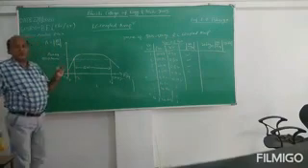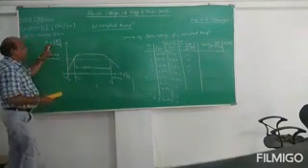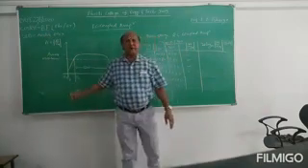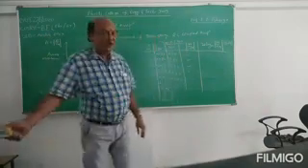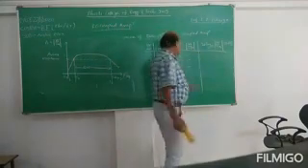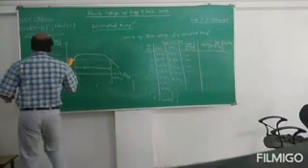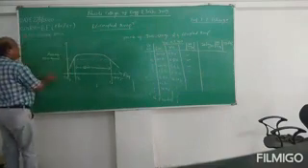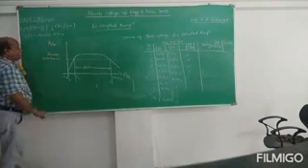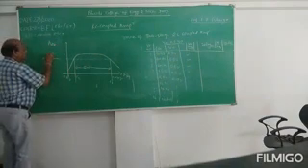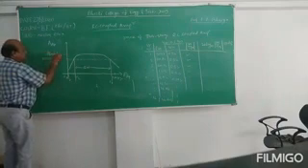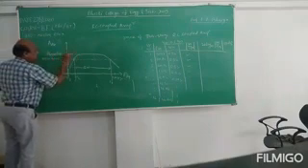And one more thing, you can plot this graph also on semi-log paper. But while plotting on semi-log, you consider this gain in decibels. So you take the gain A in dB. You will get this maximum A in dB, A max in decibels.